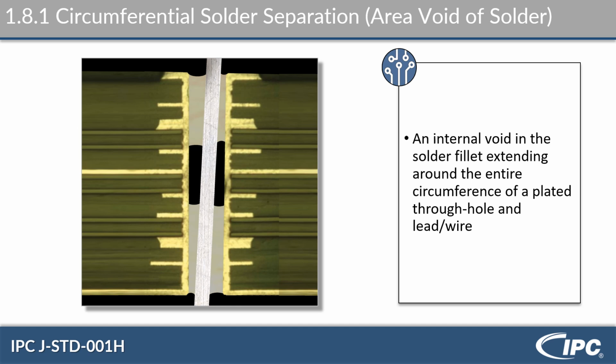This is what happens when you try to solder in from both sides. So this right here, the bottom of the board, is the solder source side. This is the solder destination side. If someone tries to solder on both, you're going to have an air pocket in here. And this is bad because inside this air is a lot of contamination. You have a lot of moisture, you have oils, just little tiny bits of dust and dirt. And that has nowhere to go, and it's just going to sit there and corrode away at your lead wire.